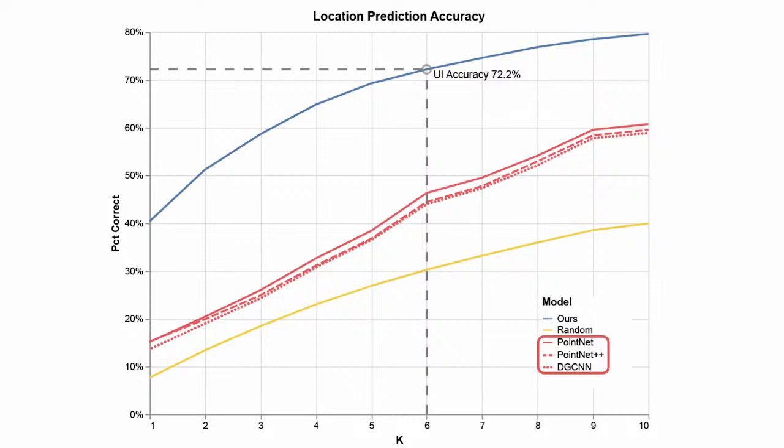Yes. Thanks. Can I ask a question about what location means in this? Yeah, so I mentioned that when you're defining a mate between parts, you have to define two things, which is where do they connect, and then what are the degrees of freedom. So this is specifying where they connect. In particular, this is trying to predict the topological entities that are going to be connecting together.